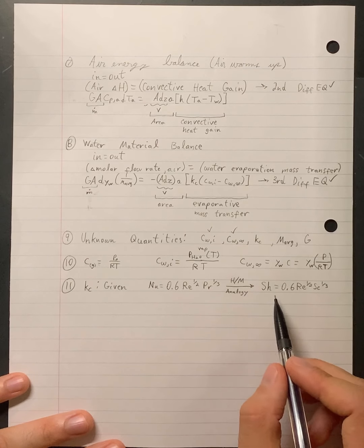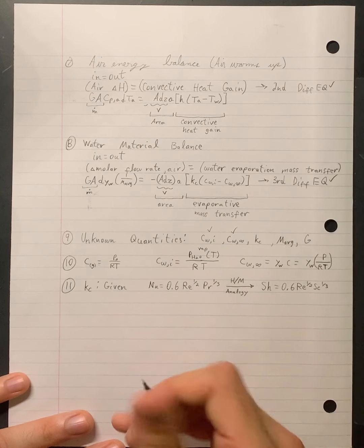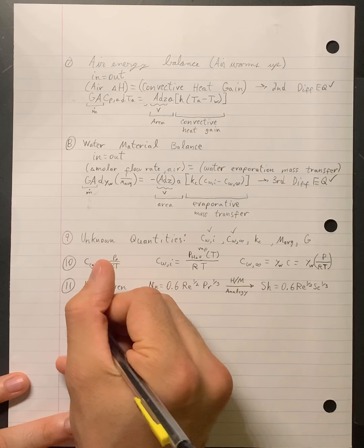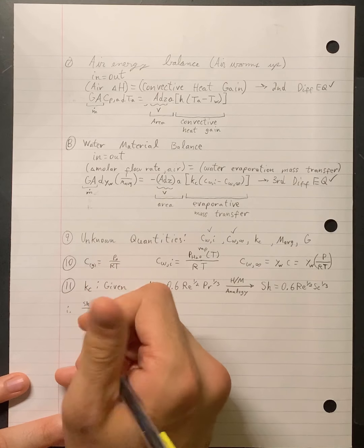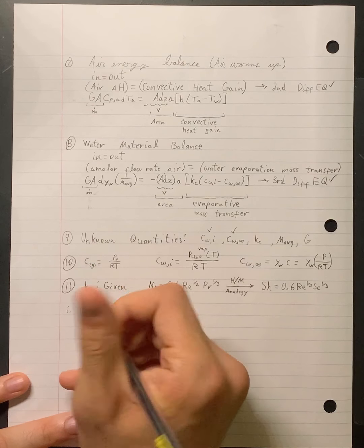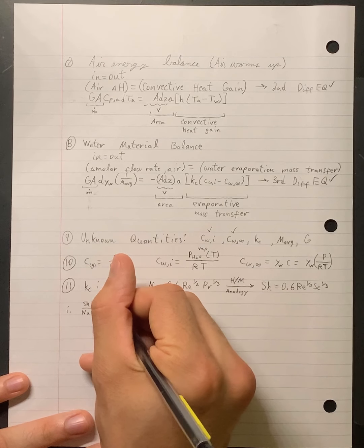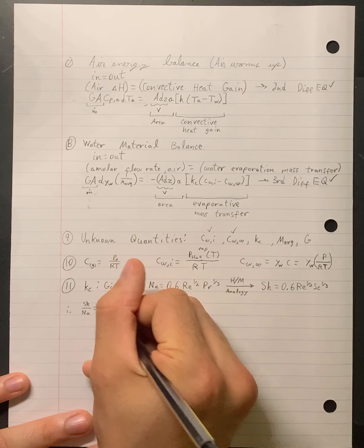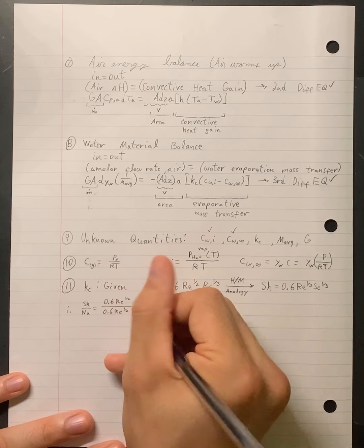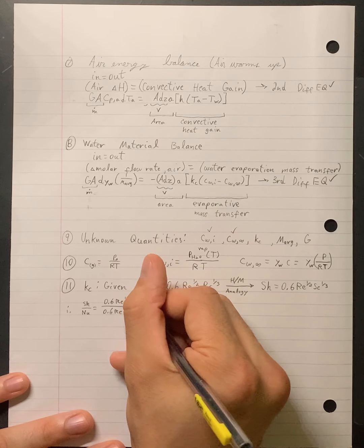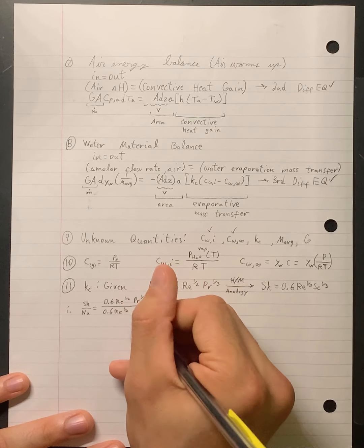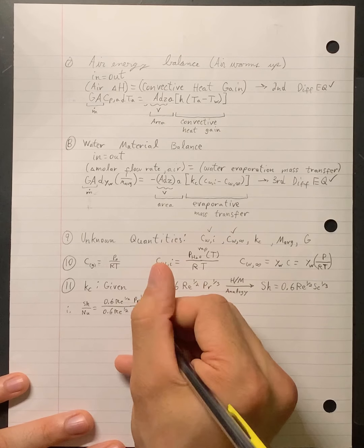And you don't have to do mass transfer experiments. You save so much time. Anyway, the first step we're going to do with these equations, we're going to divide the Sh over the Nusselt number, equals 0.6 Re to the 1/2 over the same thing, multiplied by the Prandtl number to the 1/3 and Schmidt number to the 1/3.